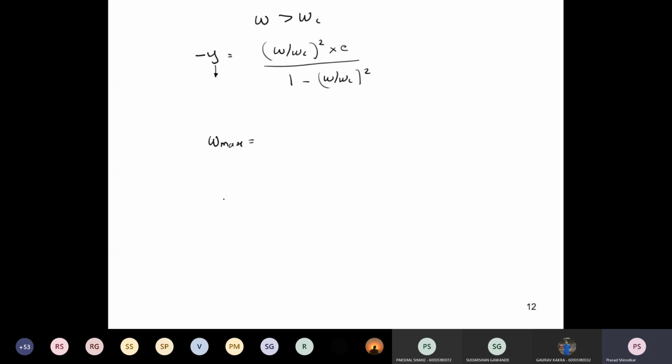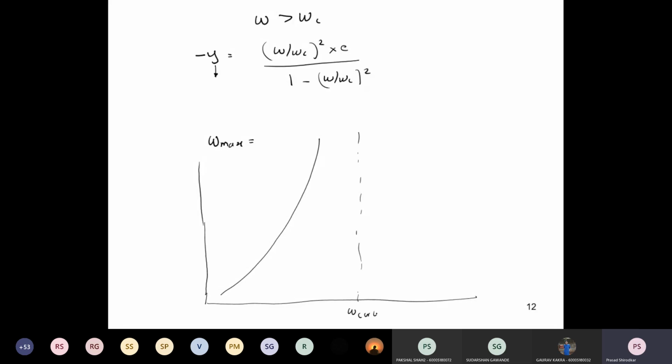Alright. So if you see the way the system is going to behave, you have your y-axis which has stress. This is with respect to omega critical or omega n that you have calculated. So at omega c or omega n, it all goes to infinity, and this is the limiting value of stress.